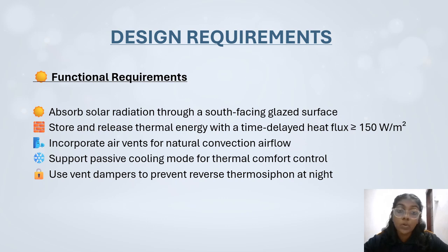The design also includes air vents to create natural convection airflow. Warm air rises into the room while cool air returns through the lower vent. Additionally, the system should support passive cooling mode to improve thermal comfort during warmer conditions. Finally, vent dampers are required to prevent reverse thermosiphon circulation at night, which would otherwise cause heat loss.